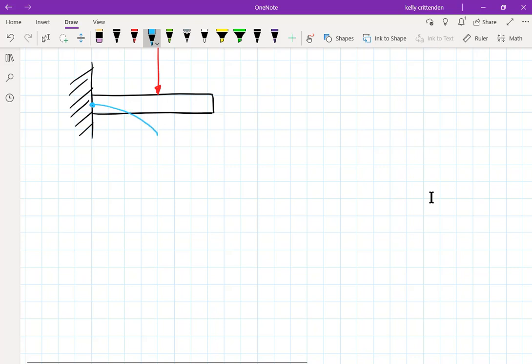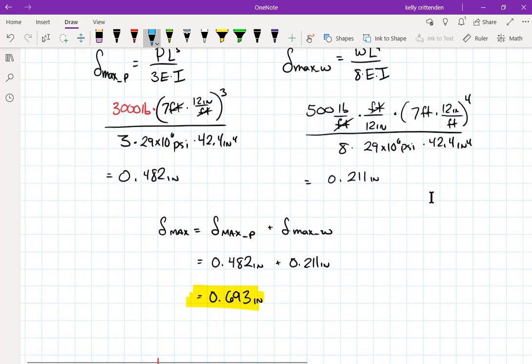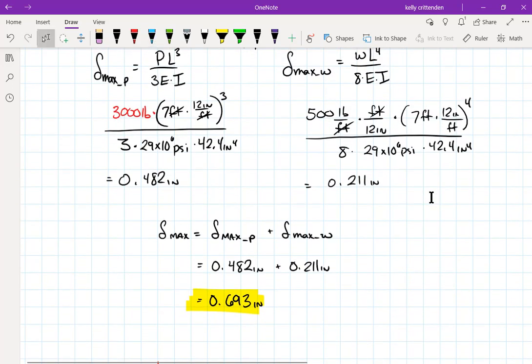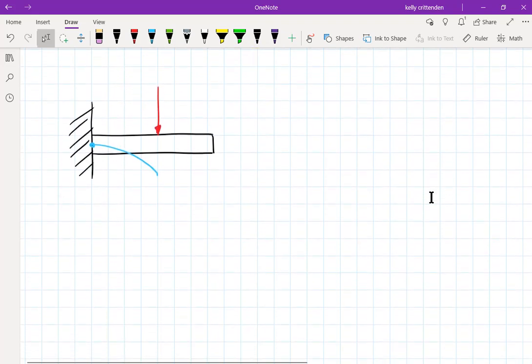But this remainder part of the beam doesn't have any force. We're ignoring the self-weight of the beam. It is possible that the self-weight of the beam acts like a distributed load all the way across the thing, and we're ignoring that. In fact, I ignored that when I calculated the stress here. So it's very possible that when we put the self-weight of this beam in, it would be over the yield strength of that steel. Anyway, ignoring the self-weight of the beam, then this last section of the beam still deflects, but basically you have a slope right here, and it just continues in that direction.